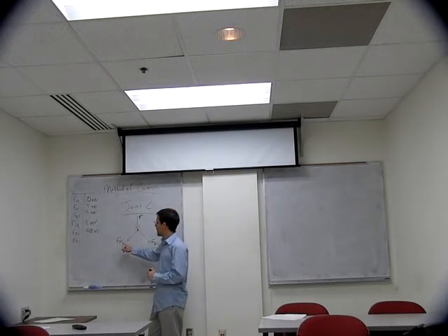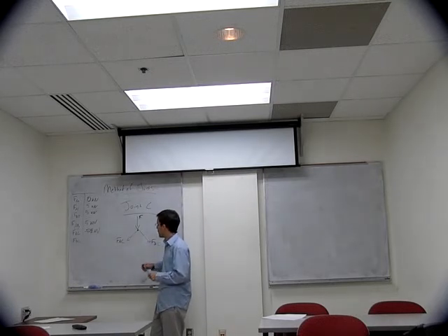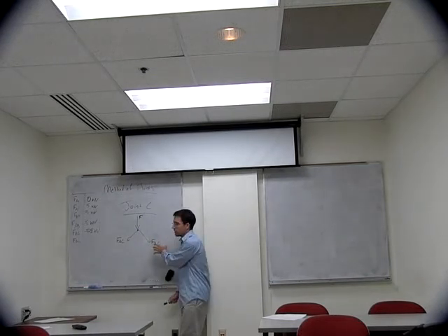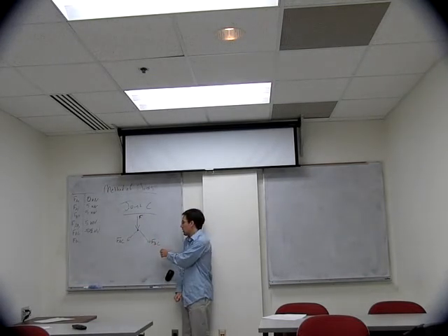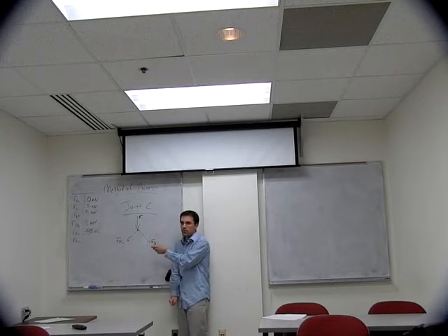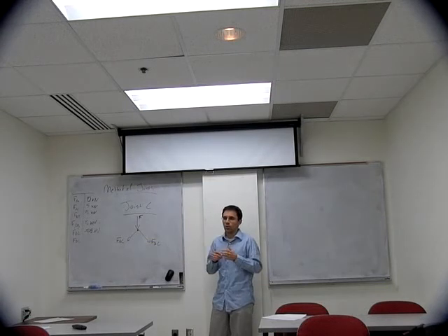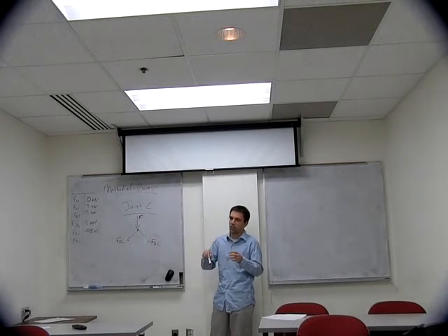But we've already seen that at least FAC is actually negative. And we can assume that since this is a fairly simple system, we know that FBC will actually also be negative. But again, it's important to keep your assumptions that you've made in the very beginning consistent throughout the entire analysis, and then go back and revise your assumptions at the end.